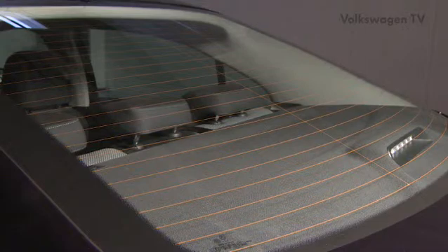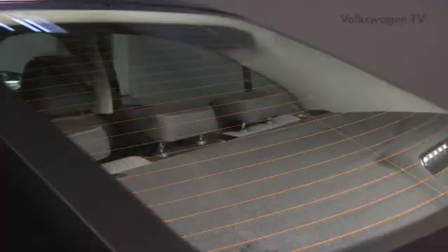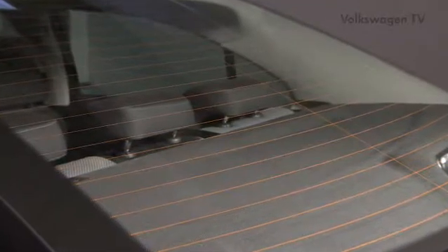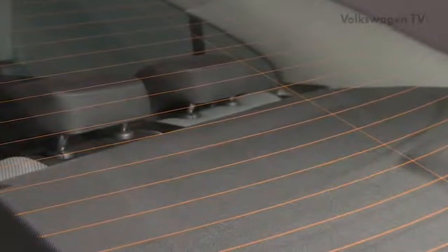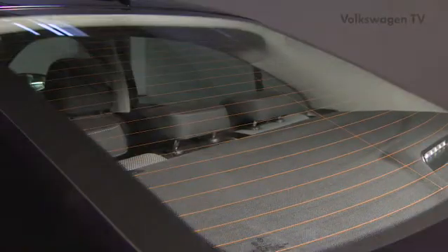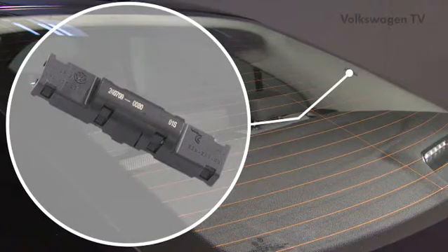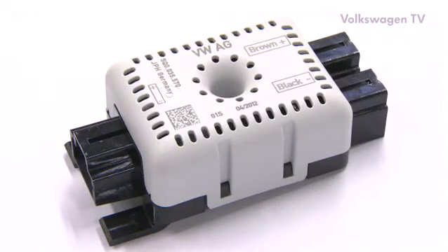Vehicles without a rod type or roof aerial are often equipped with a wire aerial in the rear or side window. The entire heating area of the rear window heating serves as an aerial. The wires therefore have two functions: heating and receiving radio signals. To filter out high-frequency signals, trap circuits must be installed. These are 2 FM trap circuits and 1 AM trap circuit.